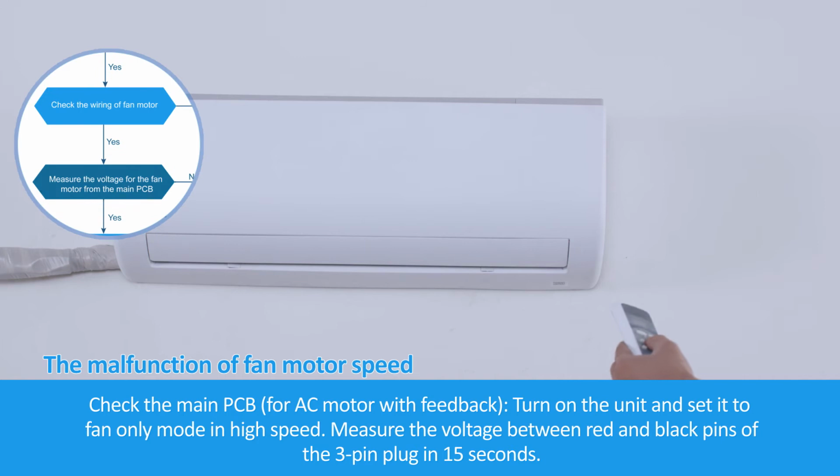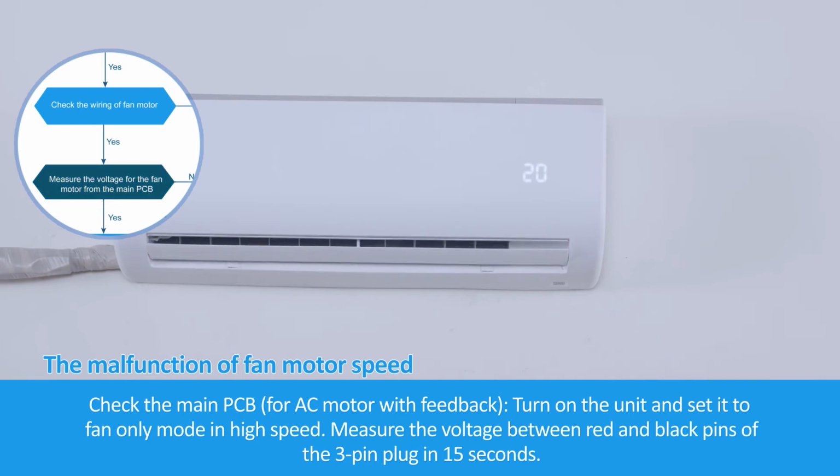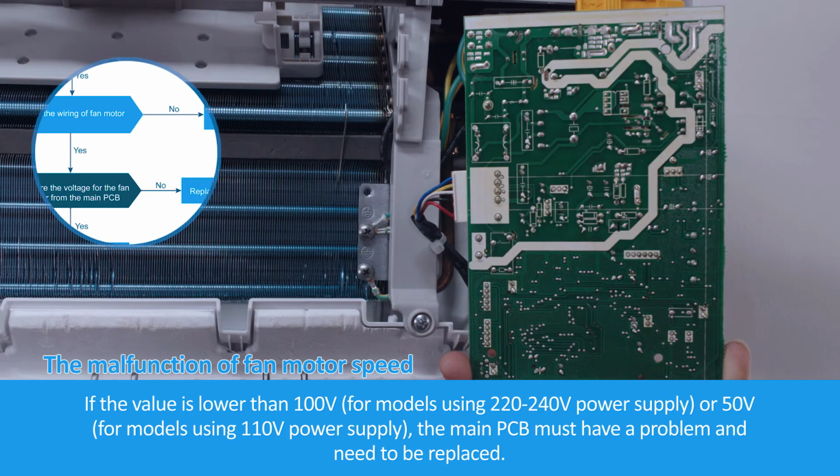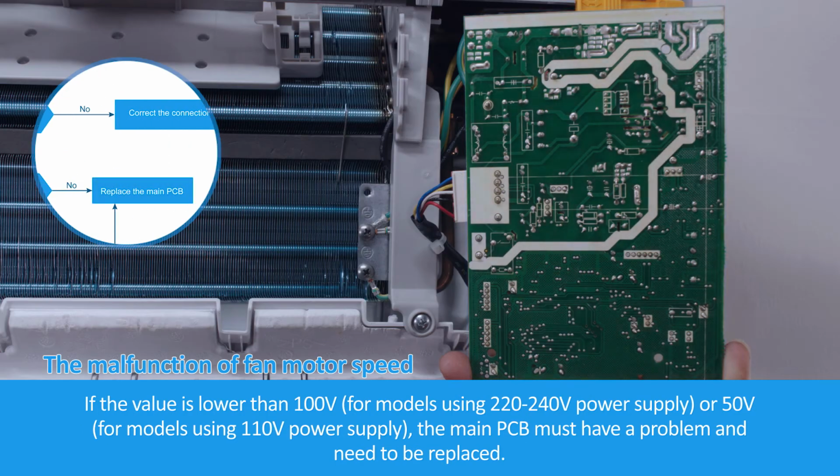Check the main PCB for AC motor with feedback. Turn on the unit and set it to the fan only mode in high speed. Measure the voltage between red and black pins of the 3-pin plug in 15 seconds. If the value is lower than 100 volts, for models using 220 to 240 volts power supply, or 50 volts for models using 110 volts power supply, the main PCB must have a problem and need to be replaced.